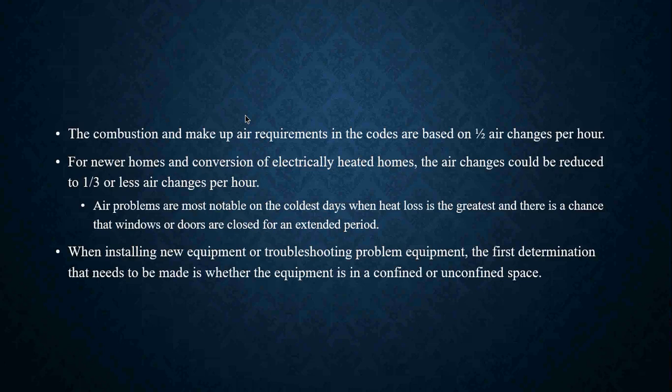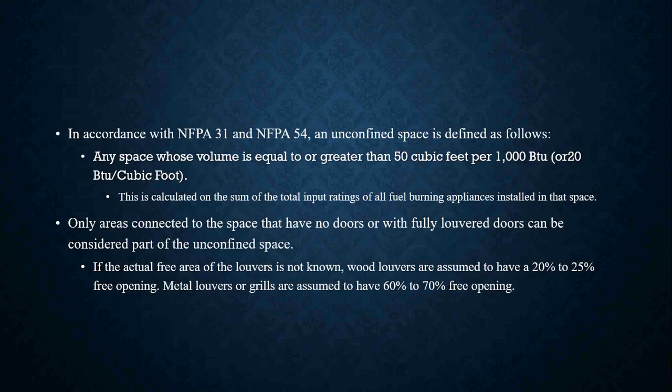Air problems are most notable on the coldest day, when heat loss is the greatest and there is a chance that the windows and doors are going to be closed for an extended period of time. That's usually when a lot of people notice that smell or problems with their air quality. When installing new equipment and troubleshooting problem equipment, the first determination that needs to be made is whether the equipment is actually in a confined or an unconfined space.